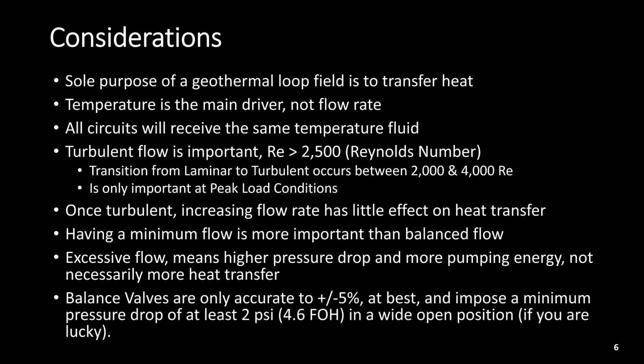And finally, balance valves, if you look at the specifications, are typically only accurate to plus or minus 5% at best, and impose a minimum pressure drop of at least 2 psi or 4.6 feet of head in a wide open position. But that's based on a certain flow rate. And if your valve is at all undersized, even in a wide open position, you can get much higher pressure drops. So balance valves not only give you the upfront cost, but penalize you with extra operating cost. So keep that in mind as one of your considerations when designing a loop field.